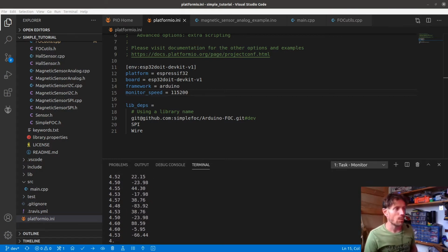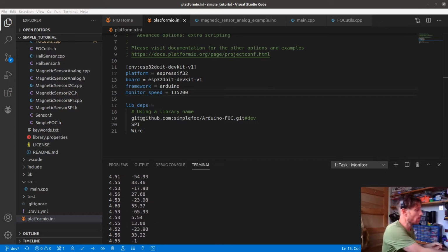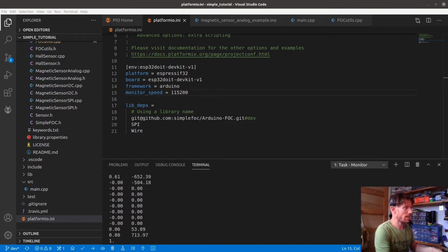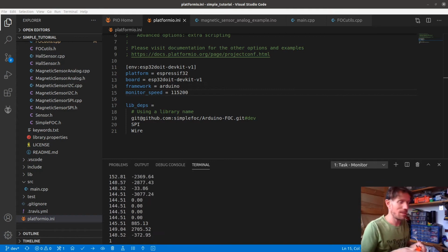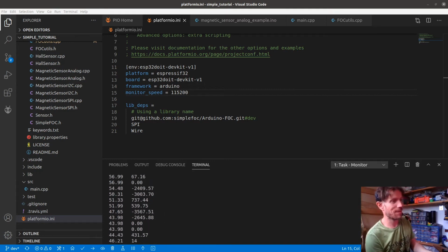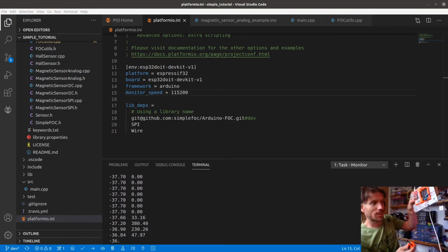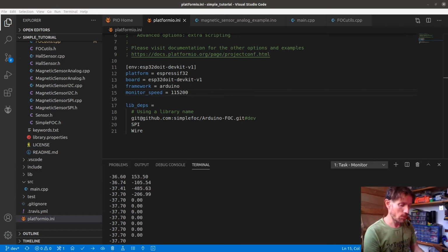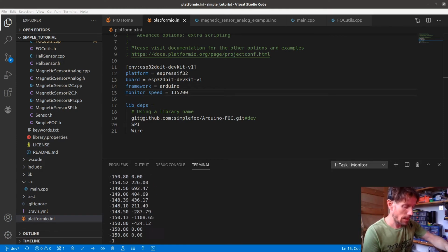So where was I? We're seeing a stream of angles in the serial. So I'll just see if I can get this. Oh dear. That's not so good. Basically the motor and its connections have come out of the board. So I'll see what I can do here. Just pop some of the leads back in. There's only 3. Basically what we're dealing with here is a small gimbal motor. It's one of those 7-pole, 2804, so 28 millimeters diameter and 4 millimeters thickness, the motor. Right, let me just make sure I'm putting in VCC. Where's ground gone? Putting in ground, and the 3rd pin is the analog pin.